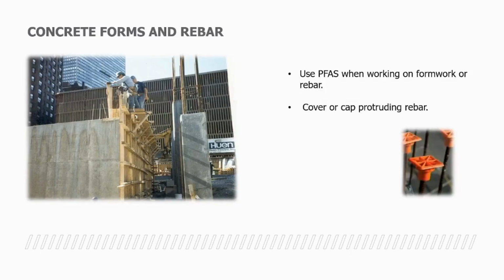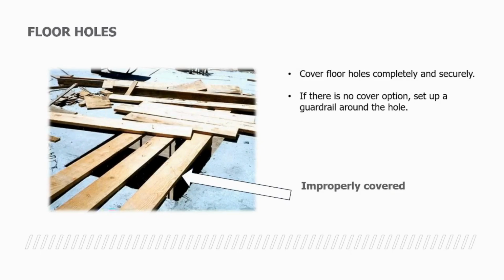On the hole opening itself, back up here for a second, if you do cover over a hole with, let's say, a piece of plywood or something of that nature, you need to write on the top of it the word hole, H-O-L-E. That way it identifies that, yes, there is a hole directly below that plywood. So once again, it is taken as a precautionary measure.